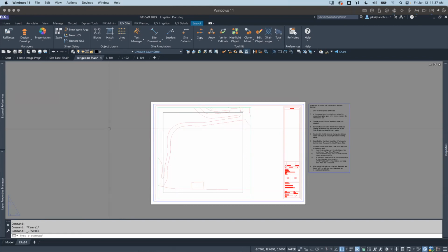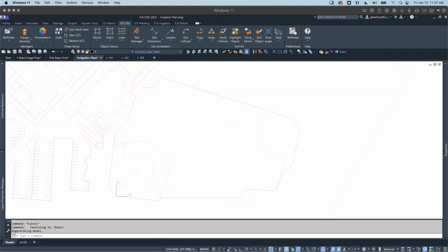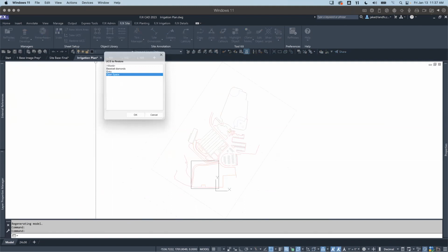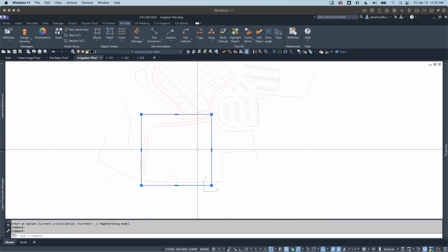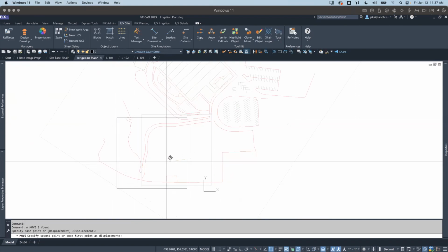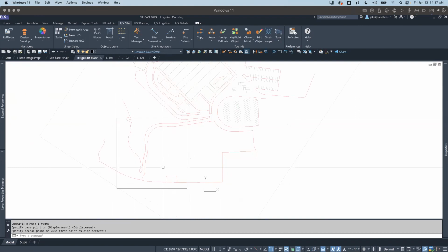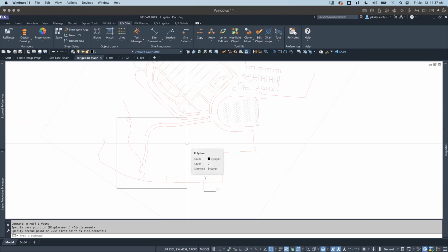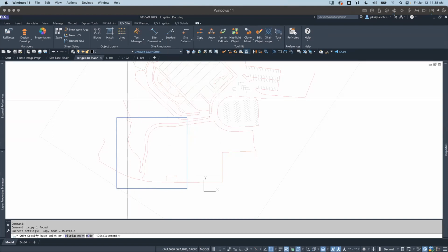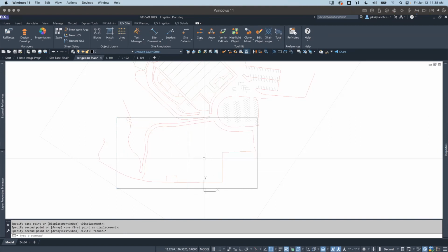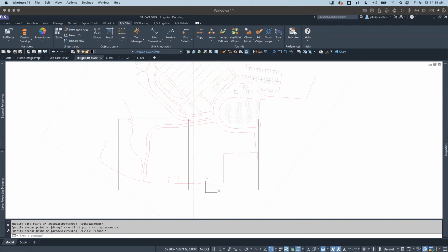Okay, so if I go back over to model space, and we'll go ahead and restore this open space view, you can see that it inserted that rectangle. That's pretty cool, right? So now I can actually move it around, and I know that I can fit this much stuff within that viewport at a 20 scale. Okay. And I can take that and copy it and line it up and see exactly how many sheets I'm going to need, right? That's pretty useful.